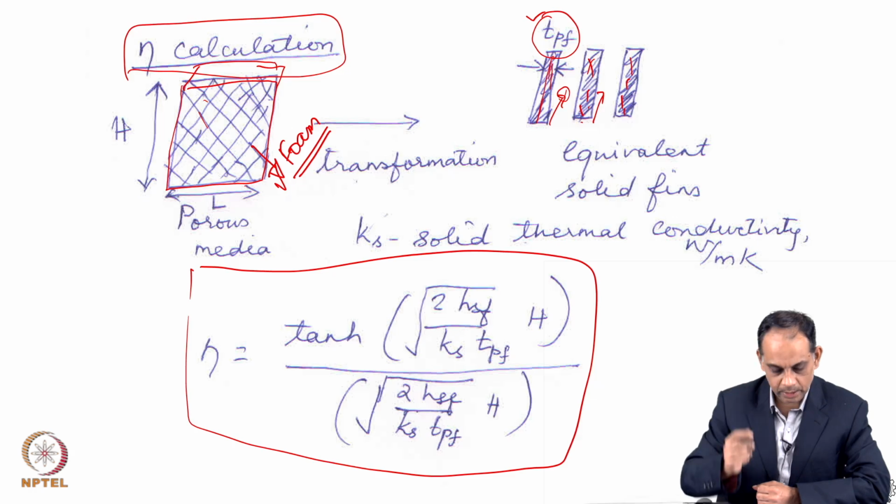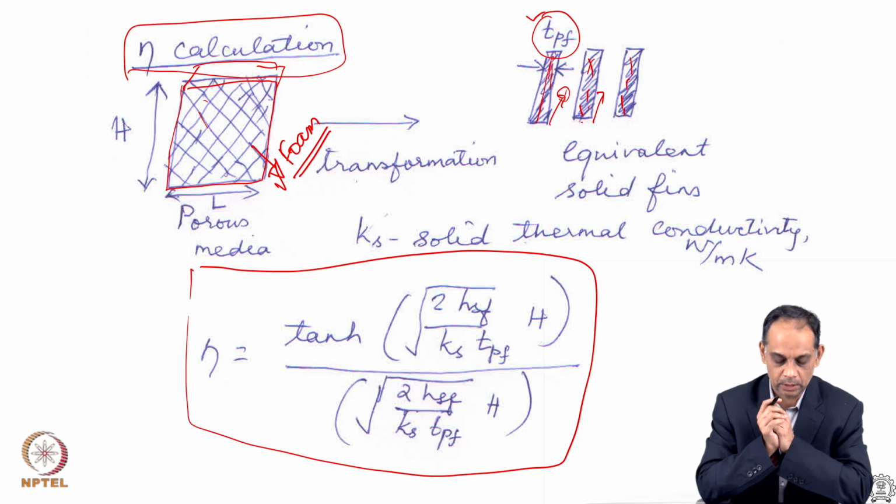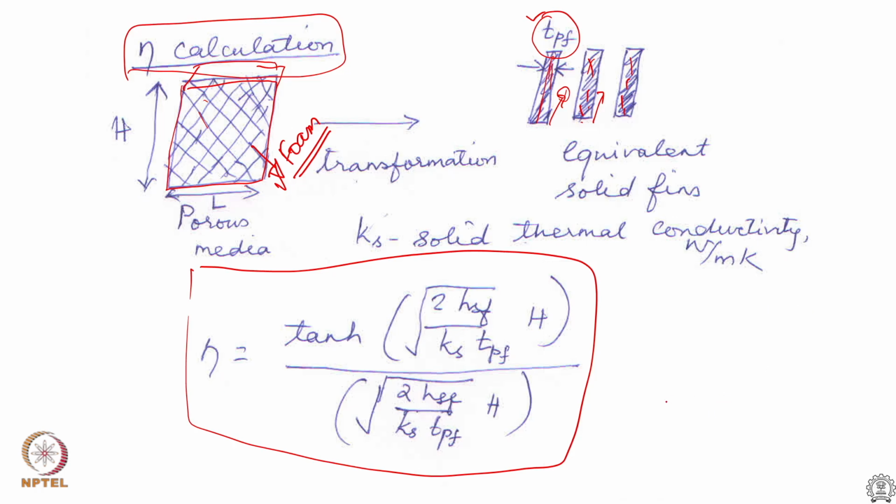The idea here is that it is not a big geometry transformation, it is just that an equivalency is thought out. For the fin efficiency, as in typical heat transfer courses, I have a fin with a certain thickness, a heat transfer coefficient and T infinity known. The bottom is T base or T wall, and the top, let's assume for now, is an adiabatic tip, with q double prime equal to zero. For that, this expression is easily obtained.